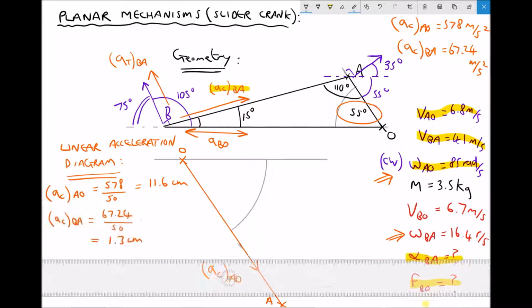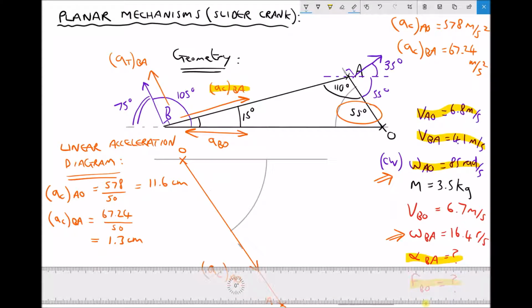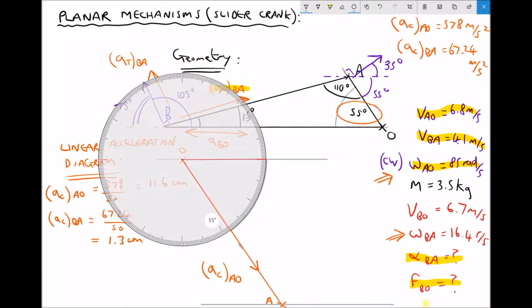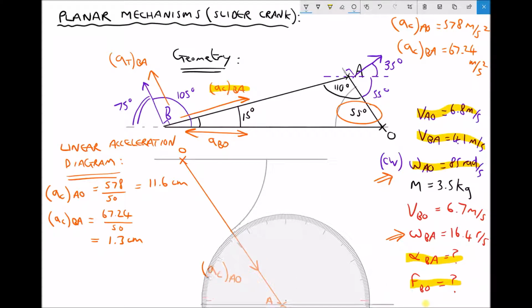I'm going to start with a second datum line, a horizontal datum. I then need to measure up 15 degrees, so I place the centre of my protractor on my point, like so, and measure 15 degrees. Again, you may need to make an index mark to ensure that you're in the right position.